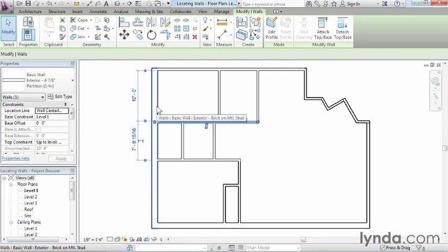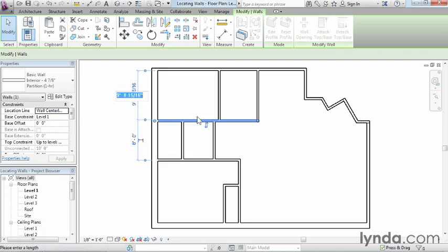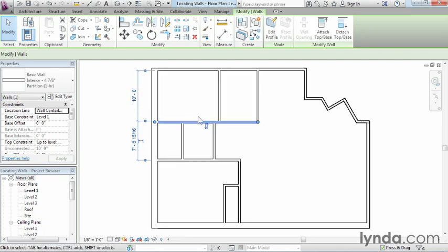Now here's a very common mistake that a lot of folks will make. They now want to set the size of this closet here, and so they immediately go to this dimension and put in their new number. But what you'll notice is the same wall that I had selected just moved and actually messed up the number that I previously typed. So I'm going to select that number again and reset it back to 10.